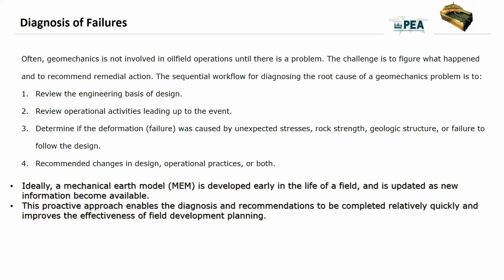The sequential workflow for diagnosing the root cause of a geomechanics problem is to review the engineering basis of design, review operational activities leading up to events, determine whether the deformation was caused by unexpected stress or rock swelling, geological structure, or failure to follow the design, and also to recommend a change in design or operation practice or both.